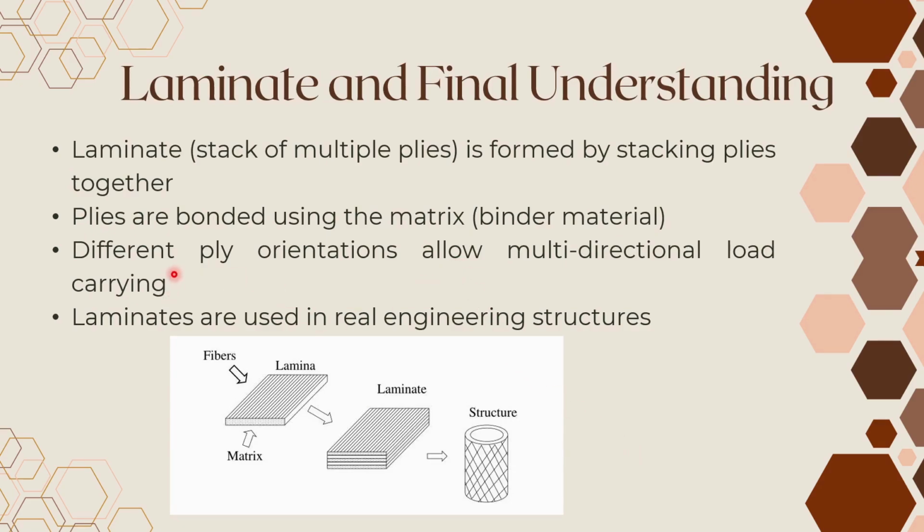to create a laminate. Different ply orientations allow multi-directional load carrying, and by carefully selecting this stacking sequence, this fiber orientation, this ply orientation, engineers will design a laminate that is lightweight, strong, and suitable for real engineering structures.